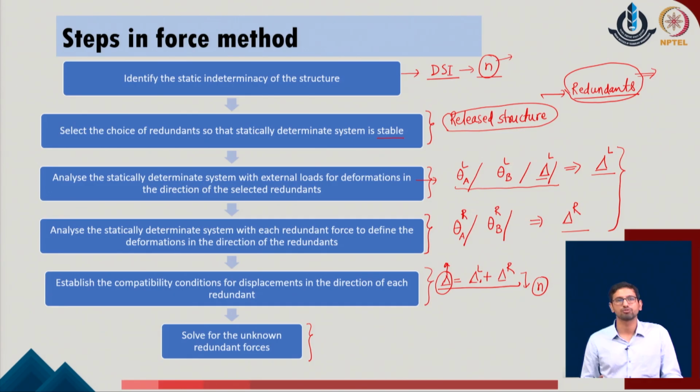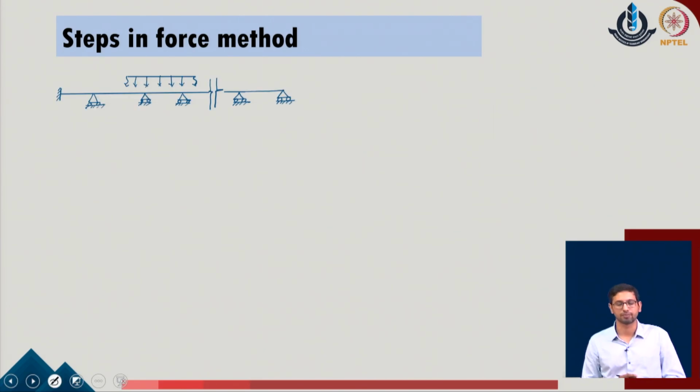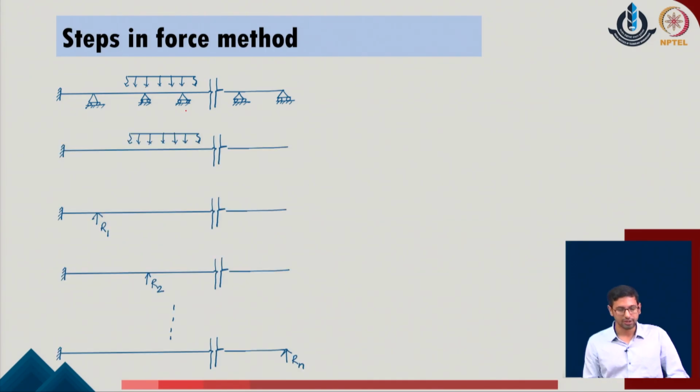We will now see this using some simple examples in the given system. So, as we define this simple example, we consider that there is a problem in which we have considered a multi-span continuous beam subjected to some loading. We considered initially that in order to consider this system into a simplified form, we have removed all these set of reactions from the given problem, because these are all the set of extra reactions which are over and above the available equilibrium equation, and I can consider the simple statically determinate system as a simple cantilever beam which has